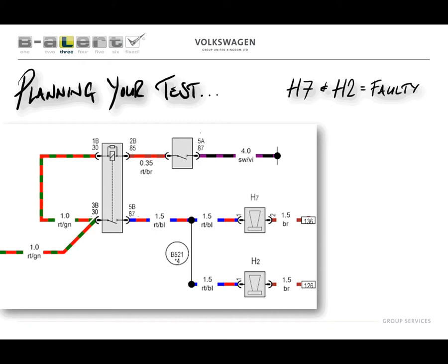But also when listening, they also heard that the horn relay was clicking. Well, when you look at the circuit and you analyse this, you can see that that means the primary side of the circuit is working. So already we've isolated the supply wires, the coil, some more wires, the switch, some more wires, the earth point. And if this was the same earth point used for the horns, that would have been even better, but unfortunately in this case it's not.